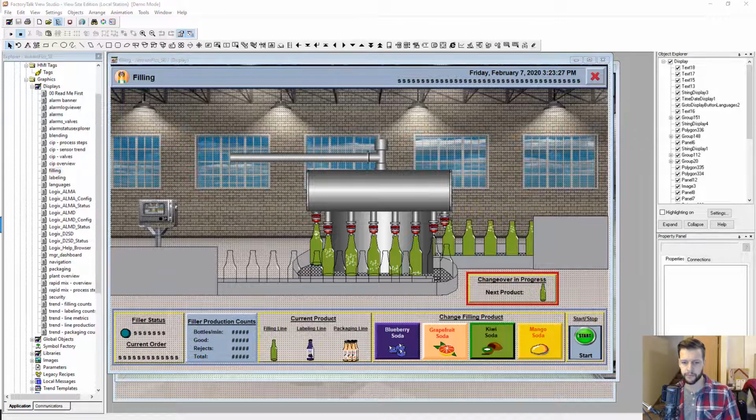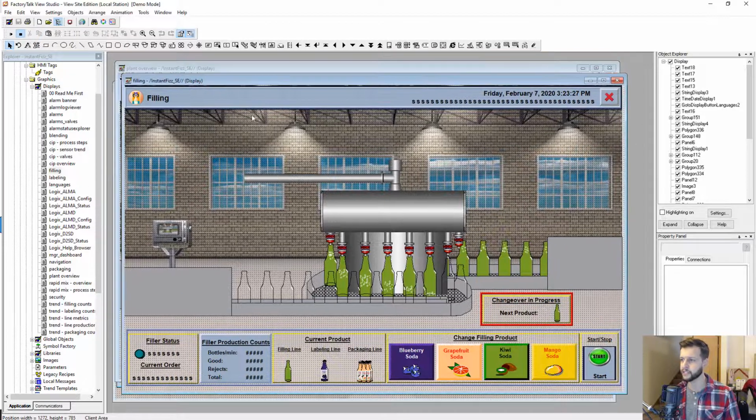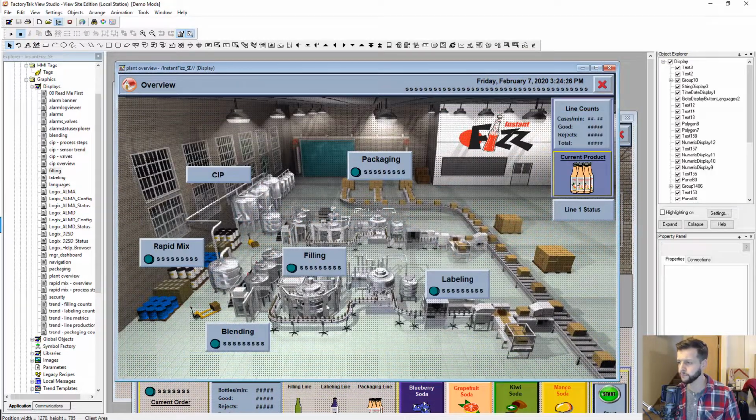So another important part of a SCADA system HMI is the alarms. Alarms are very important in automated systems, since the operator is normally just sitting back monitoring the screens. He needs to know if something in the automated plant has failed or is in alarm. So for example, if the level of soft drink liquid is getting too high in one of these tanks, if we go back to the plant overview, like one of these tanks, I assume there's soft liquid in these tanks that's being processed.